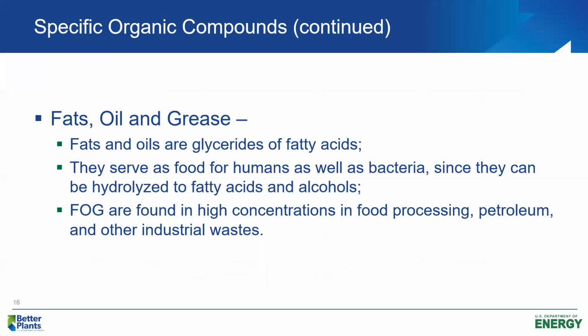But occasionally, because we have a food processing industry or a petroleum plant or some other industry that discharges a lot of oil and grease, we may have problems in the sewer system and at the treatment plant because of excess oil and grease. So for that reason, most cities regulate their industries and usually do not allow a fat, oil, and grease content over 100 milligrams per liter to be discharged into the sanitary sewer.